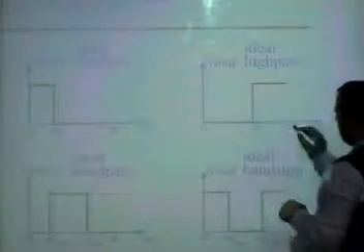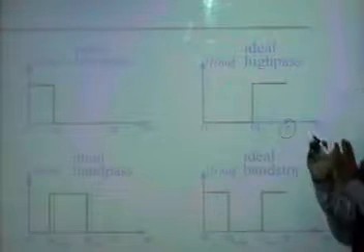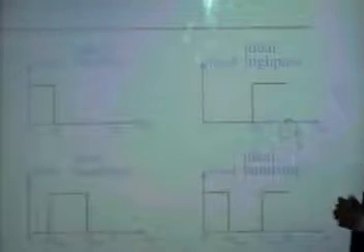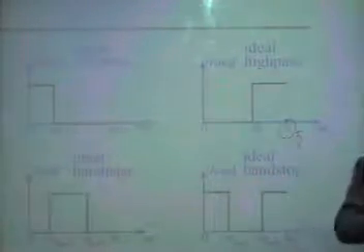You say, I want all these frequencies. Remember, pi corresponds to the highest frequency in the signal, and it relates to fs over 2. Okay, for a real signal, whatever you see on this side, you see the same thing on the other side. So in your book, you only show the spectrum from 0 to pi and not from minus pi to pi, because remember, for a real signal, the Fourier transform is symmetric.